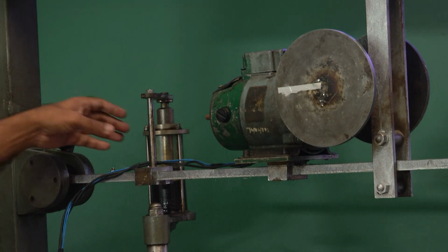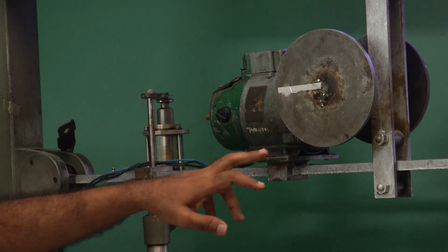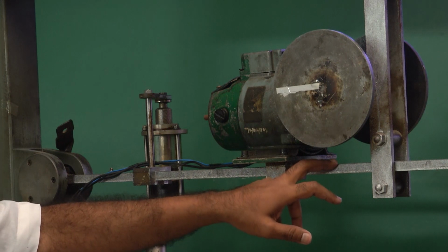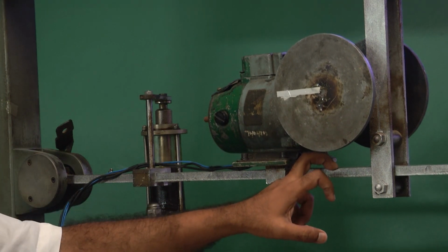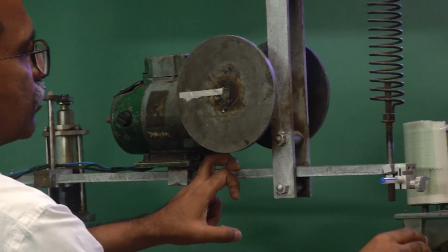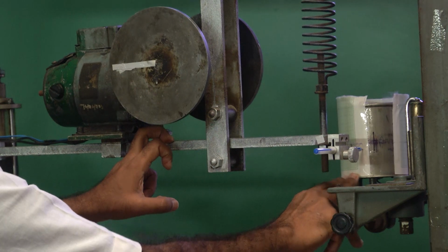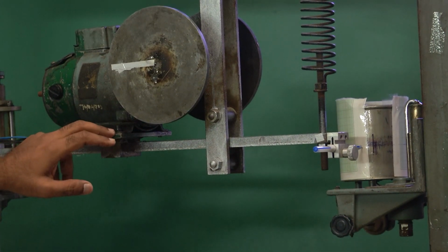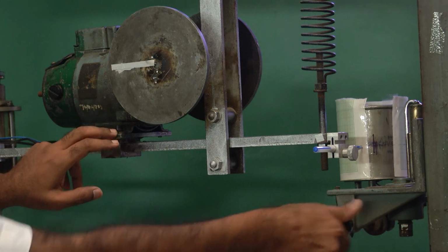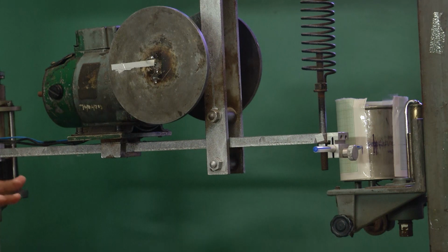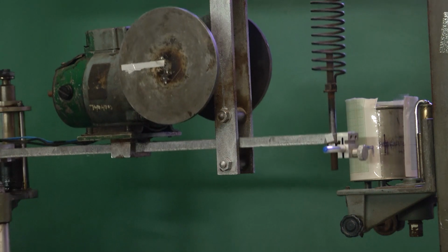Okay. Now, having connected this dashpot, you would quickly realize the effect of bringing the dashpot in, and if I perturb this, so if I now perturb this and then release, you can see that compared to the previous case where the dashpot was not connected, the amplitudes are quickly getting back to 0.